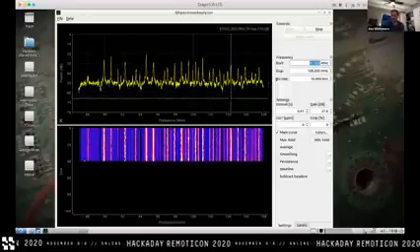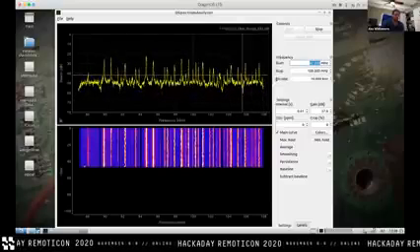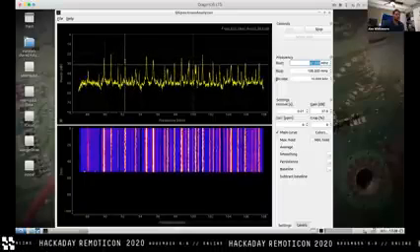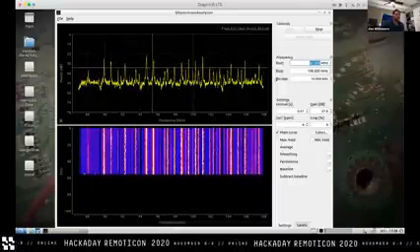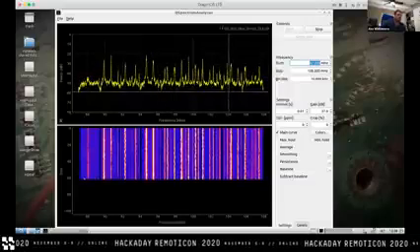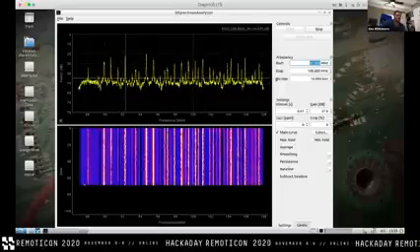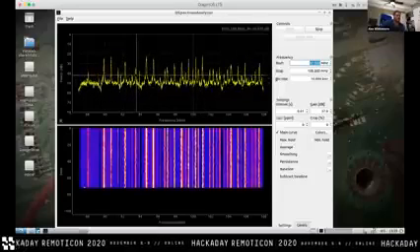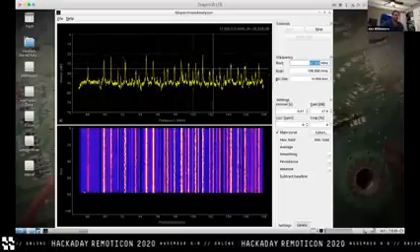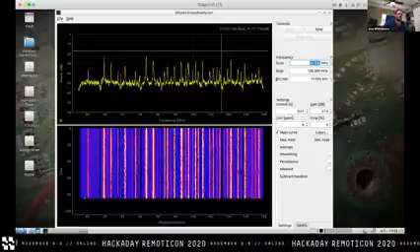On the flip side, what's cool is we see that all of these radio stations are totally coming right through. I count 1, 2, probably 3, 4, 5, 6, 7, 8, 9. I don't think so. I don't know how frequently the radio stations are actually spaced. I guess it's 0.3 megahertz. So all of these lower peaks are probably just weaker radio stations, but it's very clear that there are a bunch going on here. And this is effectively what we can do with our near field probe on our own board.